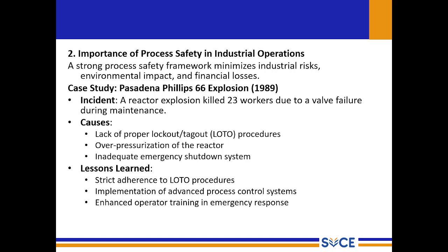So what are the lessons we have learned? A strict adherence to lockout, tagout procedures. All industries handling hazardous material must follow LOTO procedures before conducting maintenance. Equipment should be fully de-energized and isolated before maintenance work begins.